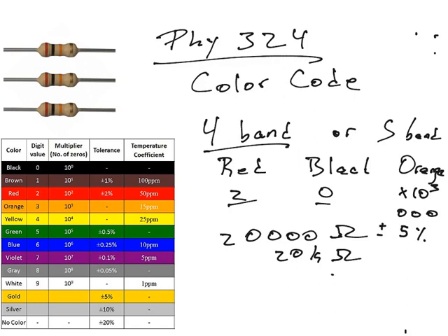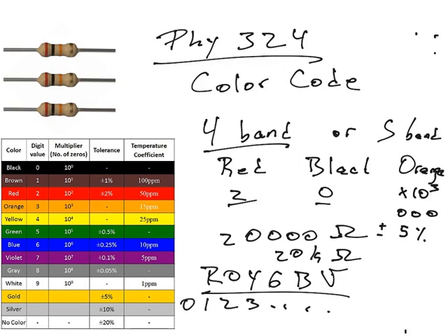First of all, you have black, then brown, which aren't standard colors in your rainbow. So you start with black, then brown, and then the rest is just your Roy G. Biv: red, orange, yellow, green, blue, violet. And then you have gray and then white. Gold and silver, of course, come after, but they're only for the tolerance. They're not part of the actual resistance itself. So if you can remember your Roy G. Biv, the colors of the spectrum, and just remember to put black, then brown before it, then it's very easy. Black is 0, brown is 1, red is 2, orange is 3, and so on.